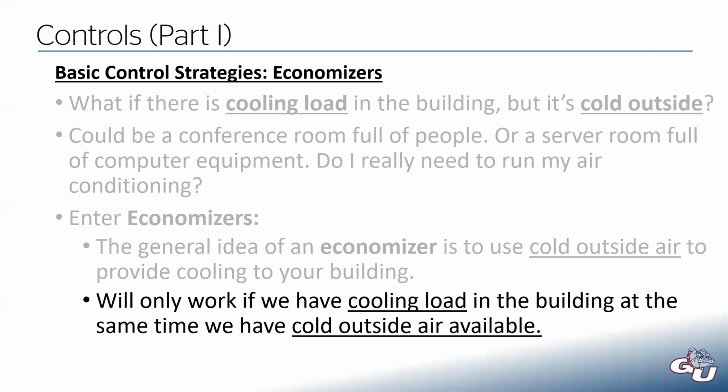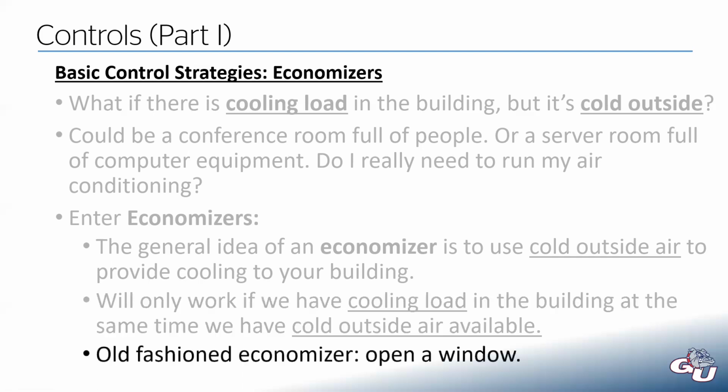But you can have those instances like the conference room full of people or a data server room where those rooms might need cooling in the middle of winter because there's so much internal heat gain going on. The first economizer, old-fashioned version, is you open a window. Oh man, it's getting stuffy in here. Let's open a window. Let's open the economizer.